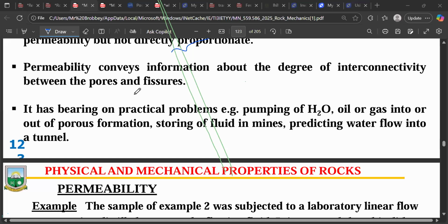The moment they drilled, we did a hole dipping. So let's say 10 meters, you achieve the 10 meters. We waited for like 4 hours and went back. I realized that the 10 meters gradually was getting to 9.8. By the following day, we were around 9.5 to 9 meters.